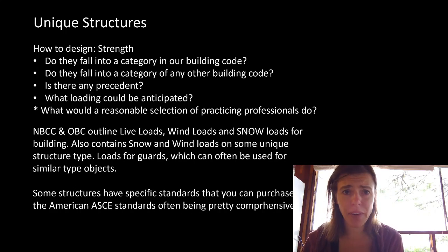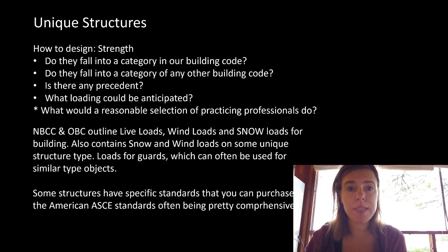Our building code is very linear and deals with square boxes with wind loads on them. Sometimes they have different shaped roofs, but that's about it. The Australian wind code has beautiful diagrams of various shapes and the wind loads those shapes can see. So it is reasonable that we as structural engineers would look into a code, because if there's a published code, there's been testing and reasonable professionals have thought about it and done something to establish a coded system for it.